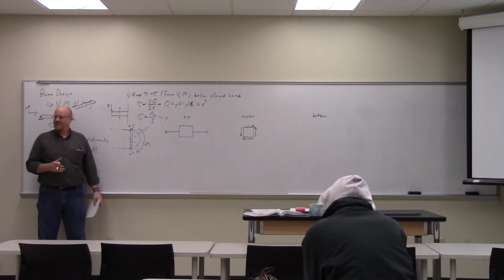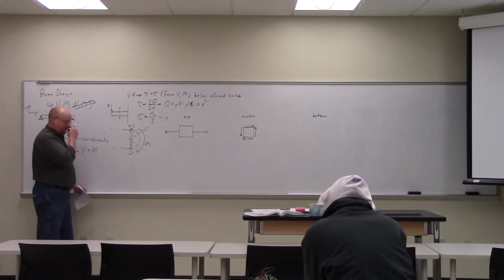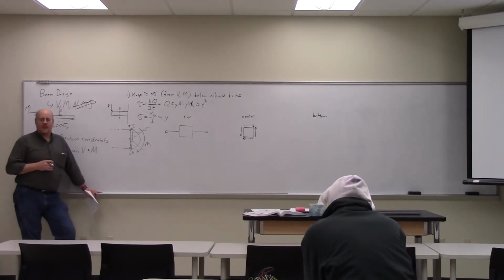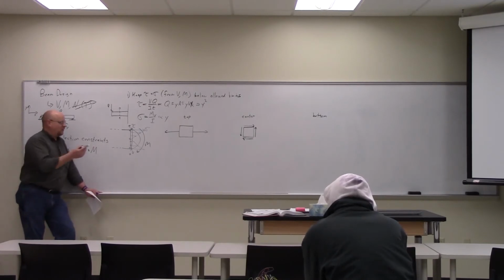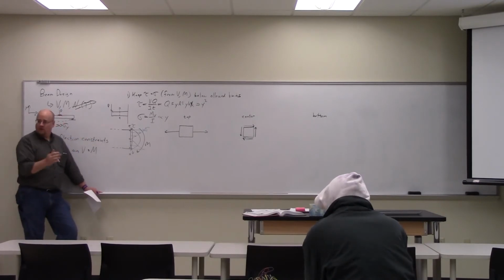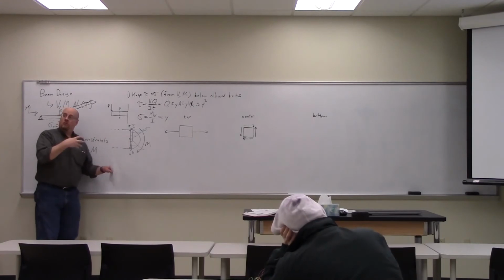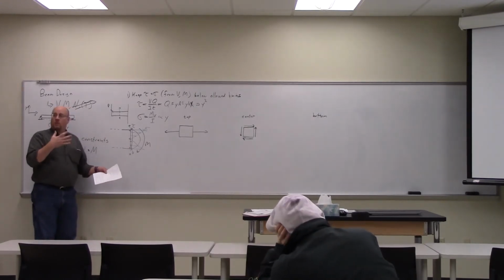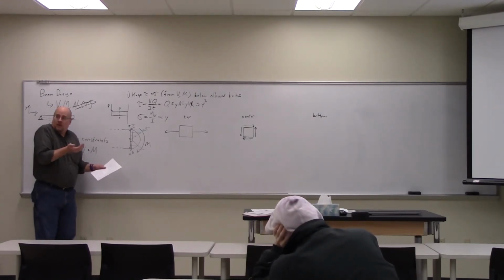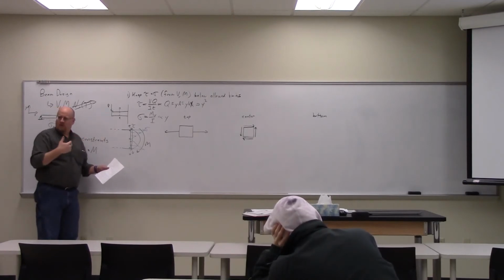Okay, is that the orientation for positive or negative shear? Again, there's a difference when we're doing internal shear. Remember, look at the moment. This is a positive moment, that's a negative moment, but in terms of the internal moment, we consider it positive if it's cupping concave up, and negative if it's cupping concave down. So for doing the internal shear and the internal moment, we do it a little differently.